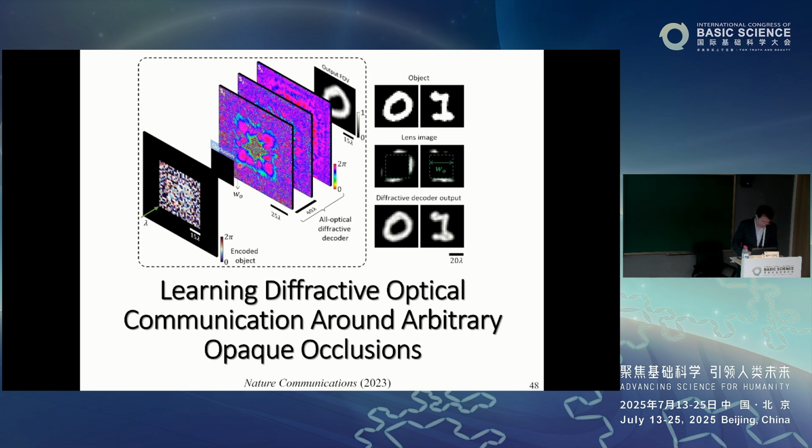The model test accuracy on the test dataset of the MNIST database is 95.5%, with the confusion matrix shown at the bottom. The results further compare 3 different network designs, demonstrating that the network can make a trade-off between numerical testing accuracy and diffractive power efficiency at the output detector, and achieve much higher matches between the experimental and numerical testing results.